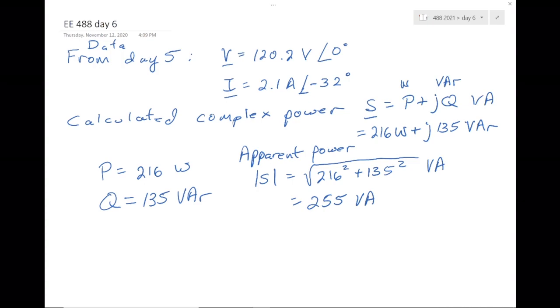Now, we talked about how reactive power is something that we calculate to represent increased losses in the power supply system that brings the electric power to the customers, to the users. We use reactive power to represent that. It isn't the losses. It's not a physical quantity, but it is proportional to the losses. As reactive power increases, losses increase. That's about all you can say. You could write an equation. It would be extremely complex.